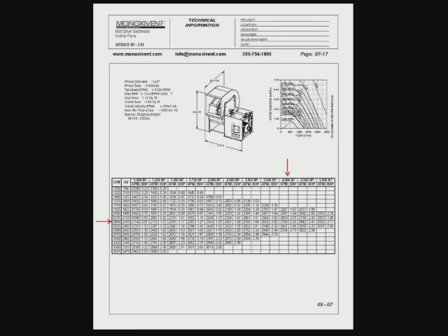It's right in the middle, right where you want to be. There's room to wiggle in this case. You could speed the fan up a little bit if we wanted to get 4.5 to 5 inches of static pressure out of it, or there may even be enough room there to add another hose drop to get another 300 CFM out of it if we were to speed the fan up a little bit, as long as we didn't alter the static pressure in the system tremendously.